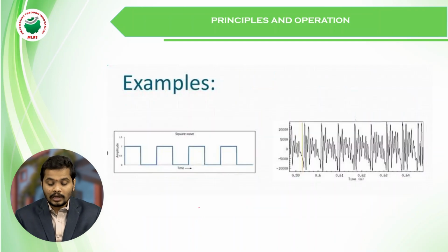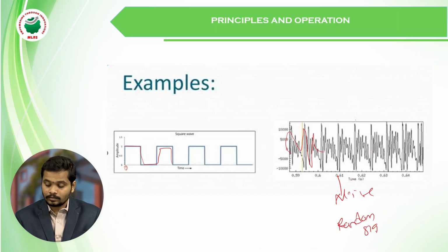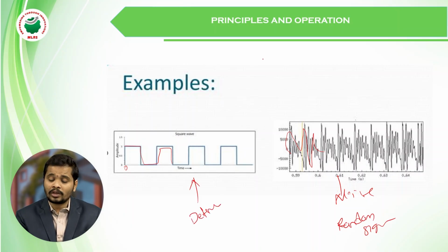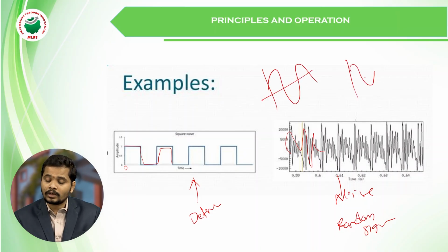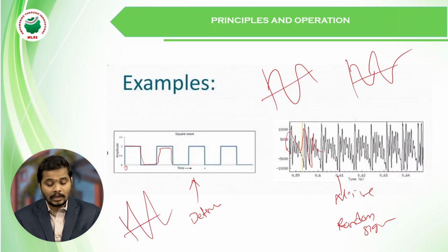They can't be predicted. For example, if you see here, it is a square signal with some time period. If you see here, it also has a time period and all the things, but you can't write a formula for this. Yes or no? It is noise. This type of signal is called a random signal. And these are the signals which are nothing but deterministic signals. You have different sinusoidal and cosine waves, and triangular waves, anything which can be written as a formula. Those are called deterministic signals. Those which can't be predicted by a formula or anything can be called non-deterministic or random signals.